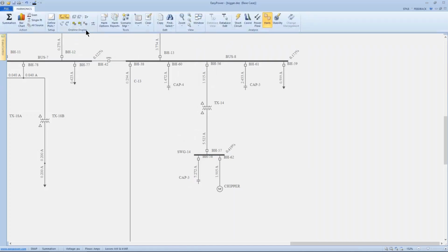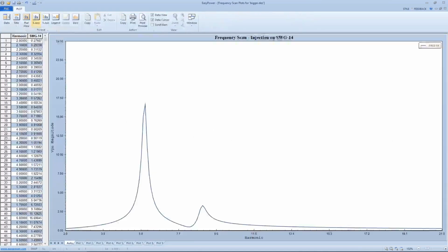As we look at the current flow, we can tell that this harmonic creates some sort of resonance. To look at the resonance on this particular bus, just by the fact that we added that capacitor, we can see that it exists now right at, looks like, the sixth harmonic. Back in the day when this facility was built, there was no intention of having anything outside of 60 hertz circulating around our plant, and so this type of resonance really wasn't causing a problem.